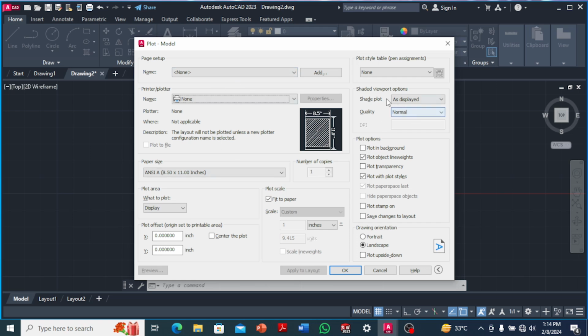So once you see this, it brings you up to this setup. Now remember, this same setup is the basic setup that you always use to document any of your drawings on Autodesk AutoCAD. Whatever version you are using, your Ctrl P still serves the same purpose, and your plot still means the same thing. So now, as you can see on this page setup, you have your name. You can easily import a setup from any site online. But I wouldn't suggest you do that, because some people's setups might differ from the one you want. So let's create our own setup.